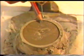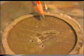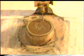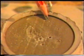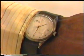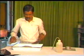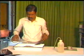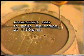After the elapse of initial setting time, observations with annular attachment are made at appropriate time intervals till the needle makes an impression on the mold while the attachment fails to make any impression. Final setting time will then be equal to the difference between the moment water is added to the cement and the time at which attachment fails to make an impression.